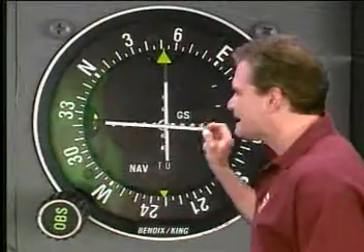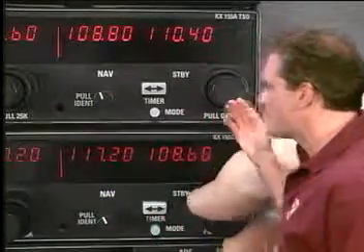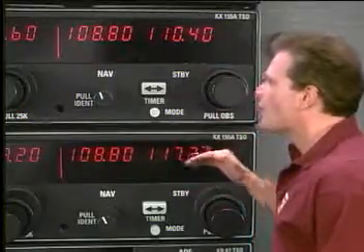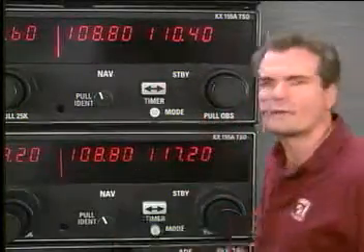And that means you'll have time to focus on tracking the localizer and glide slope with more precision to end up in the best possible position for a smooth, safe transition to the landing. When you set up your avionics, you'll want to start with your nav radios. If you're still navigating on the airway, set the airway up on your nav2 radio so you can go ahead and set your nav1 radio up for the ILS.